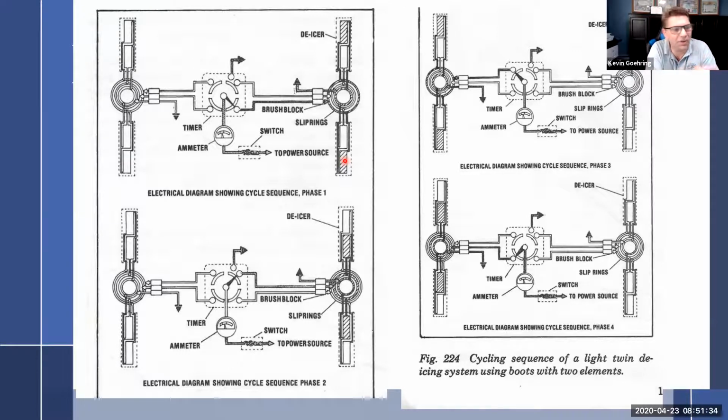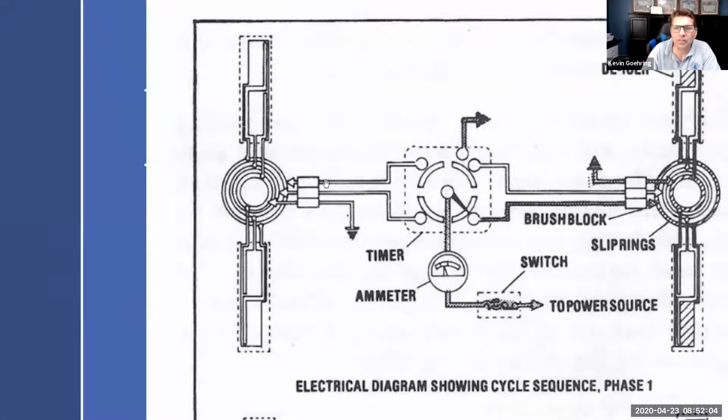And that's really simple. It's no different than how you would do it inside of a generator or an alternator. Alternator is actually more accurate. And you just use slip rings and brushes. So that's what this represents right here. We have a wire, and don't worry about this right here right now. We'll talk about that later. So we have a wire that's coming in, and it's got a carbon brush, and I'm going to zoom in a little bit. I was looking at one of the pictures I have. So that carbon brush is touching this ring, and this wire works a certain heating element within the propeller. All right, and then this wire comes to another one that heats up this certain element in this propeller.